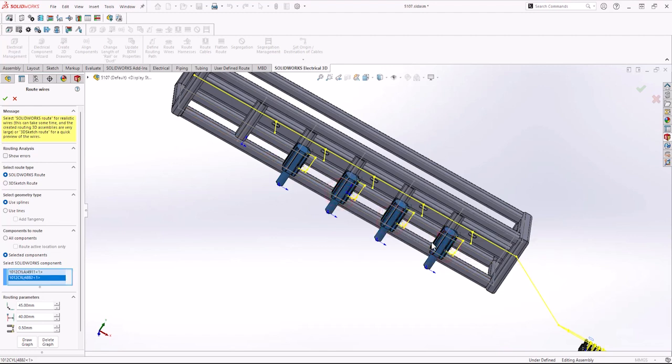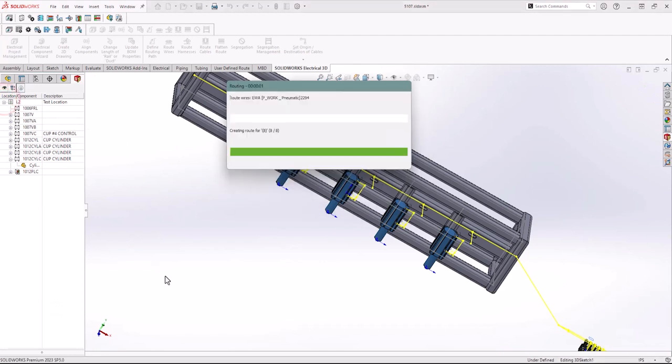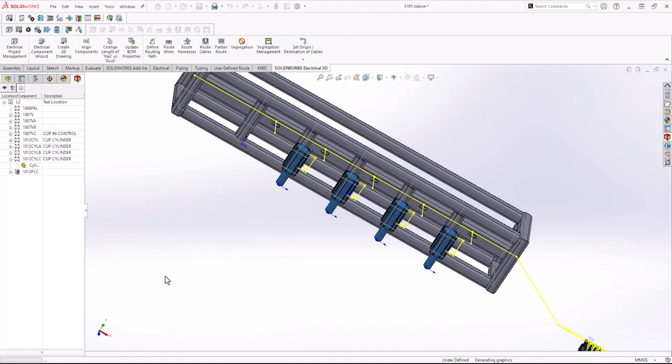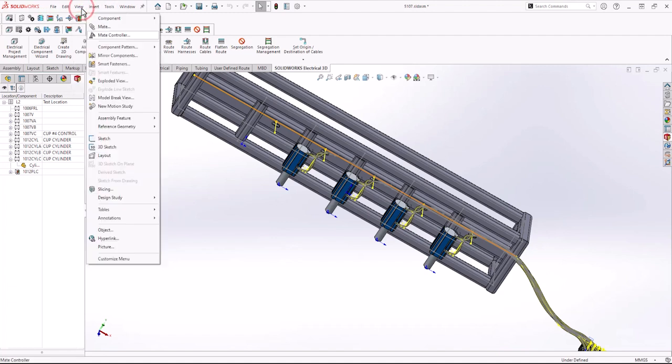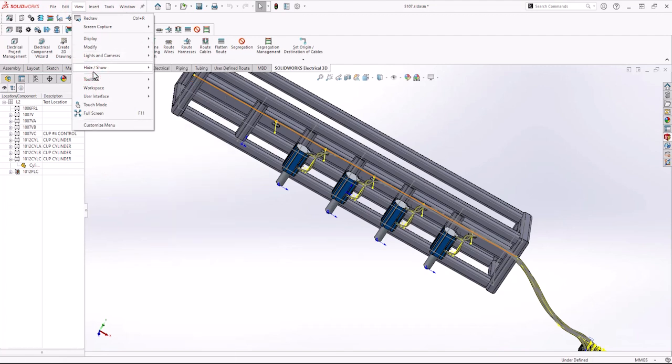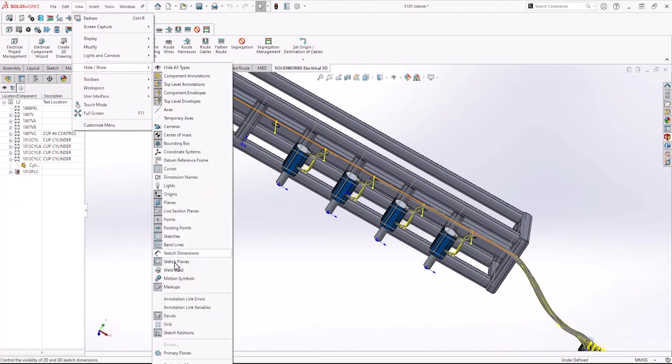With SOLIDWORKS Premium, you are literally running from point to point, and then you're having to adjust each one to go through those slots and follow whatever you want, but you're pushing and pulling and editing each route individually. Here, all we do is simply push the button with those parameters. It follows that path and does all of them at one time.